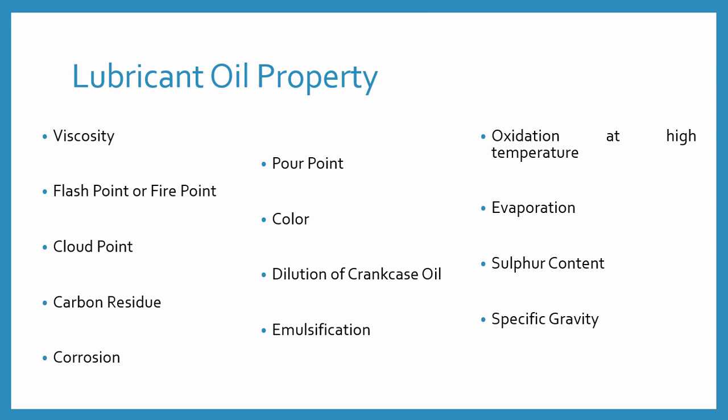A lubricating oil can be considered as a series of parallel layers moving one above the other. Any two layers will move with different velocities; the top layer moves faster than the next lower layer, due to the viscous drag.